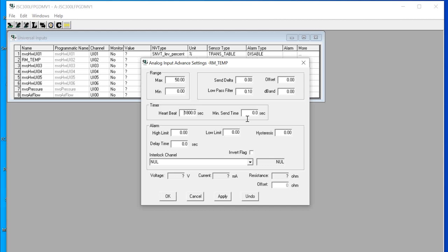Then you see how it goes, because some sensors are not good. If you use AC as the power supply, the reading will be fragile. Then you change to DC as the power supply, maybe it will be stable. Don't use AC as the power supply. Maybe you can try that, maybe you can use the office testing. So you face this problem.